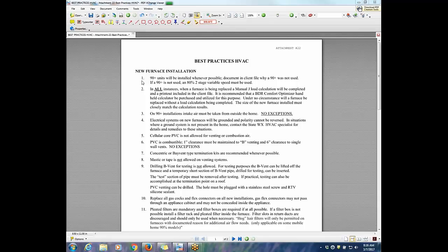The furnace was in an attic. What's the problem with it being in an attic? Well, the condensation can freeze. Aha. Okay, you could run into a situation where you can freeze those furnaces up. So that may be a compelling reason why you don't want to put a 90% furnace in a particular place, attic or crawl space. That actually came up recently. There are things you can do to prevent them from freezing. Sometimes those things that you can do are, you know, cost prohibitive or just take too much time or money.